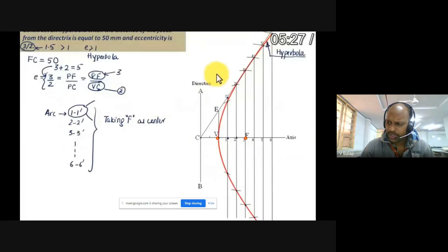Buy minimum 10 number of drawing sheets. One you keep as the support. That means at a time you need to use two drawing sheets. Keep the other extra sheets in a safe place, and at a time you can use two drawing sheets. One is support, the other one you are actually drawing on. Fix the drawing clips on the drawing board. Use the mini drafter.